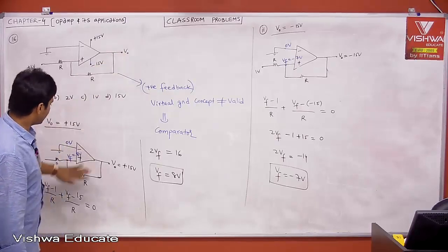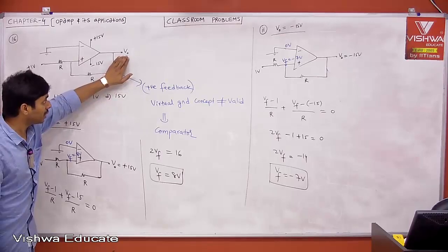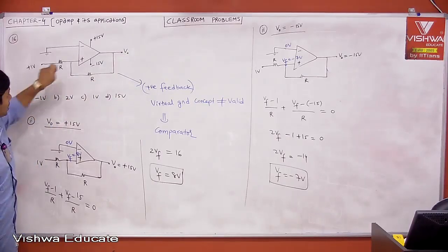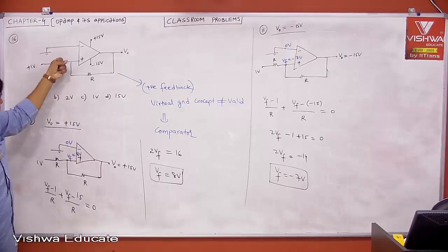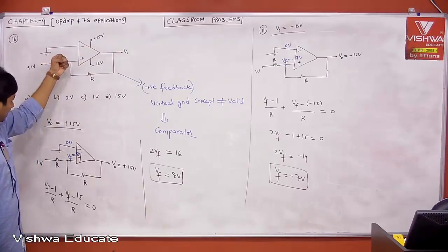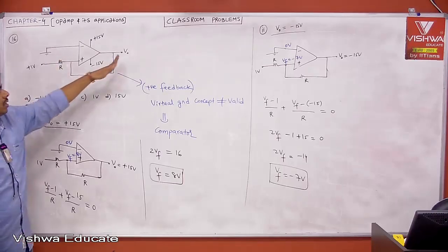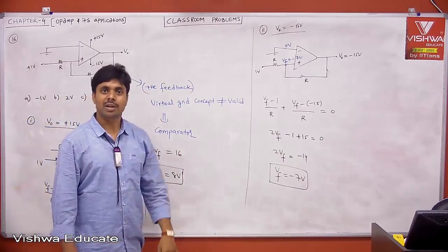Let us say this is the scenario, when V0 is plus 15, then to disturb the state of V0, people apply some trigger at plus. When you apply some trigger at plus, then momentarily you pull it down, then your V0 will become plus 15 to minus 15. Once you apply the trigger and pull the node, V0 switches from plus 15 to minus 15, it will stay there only, because it is also stable.